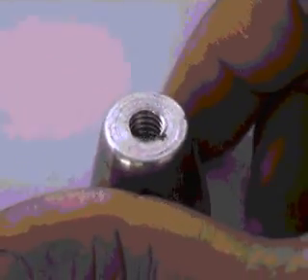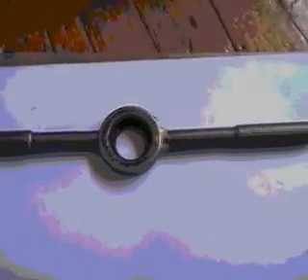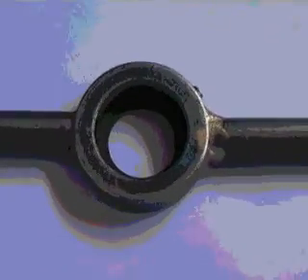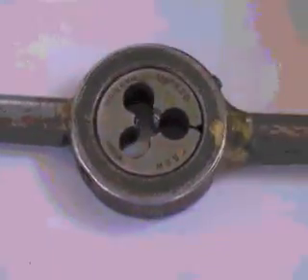So this is the complete tap. We'll show you the side view of this tap. You can see the tap inside the job. This is the complete finished thread made by the three taps which we use. This is a die handle. The die handle is used for making threads on the outside. And this is a die. The material is again the same, high carbon steel, hardened and tempered.